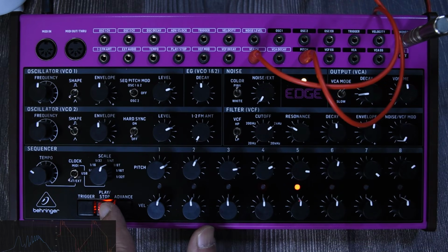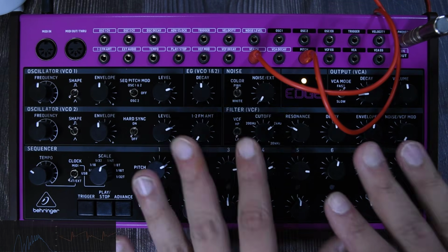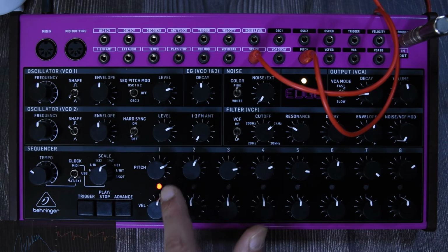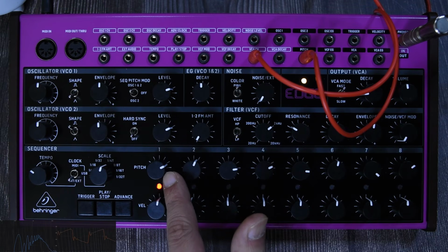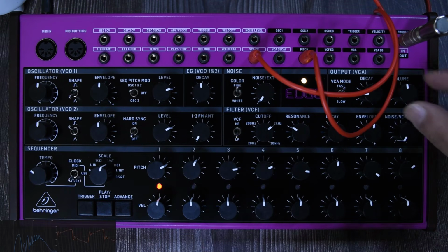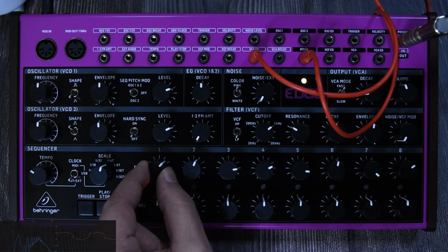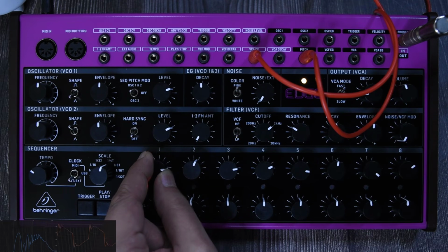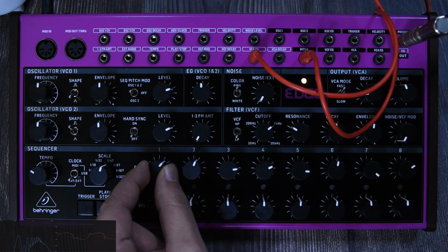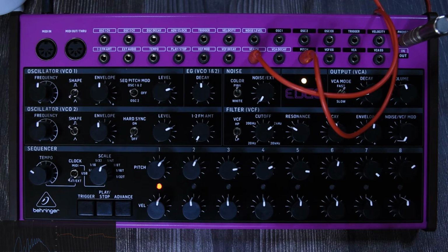And just to give you an example, I'm going to be stopping it on step number 1. Notice I'm not playing anything. So when I stop right here and this voltage is outputting, I guess it's 2 point something, the volume stays right there at the top. It's not stopping. It's keeping the volume open. So if I move it down, it's going to go to full silence. But if I go up, it's going to go loud. So this is something that you need to be aware of when you connect something to the VCA CV.